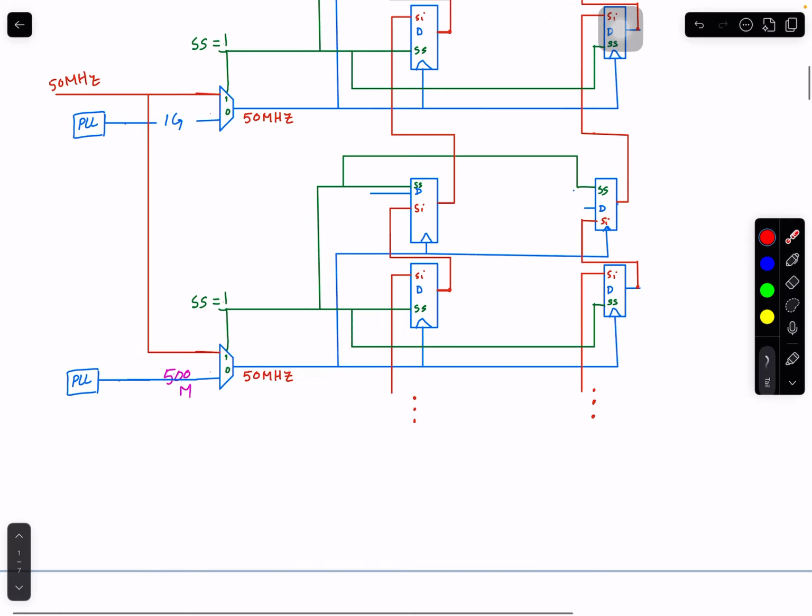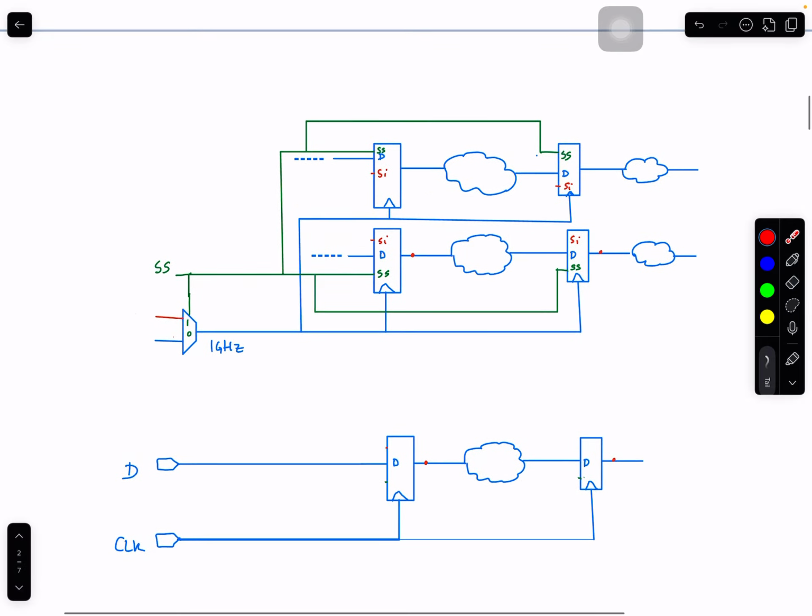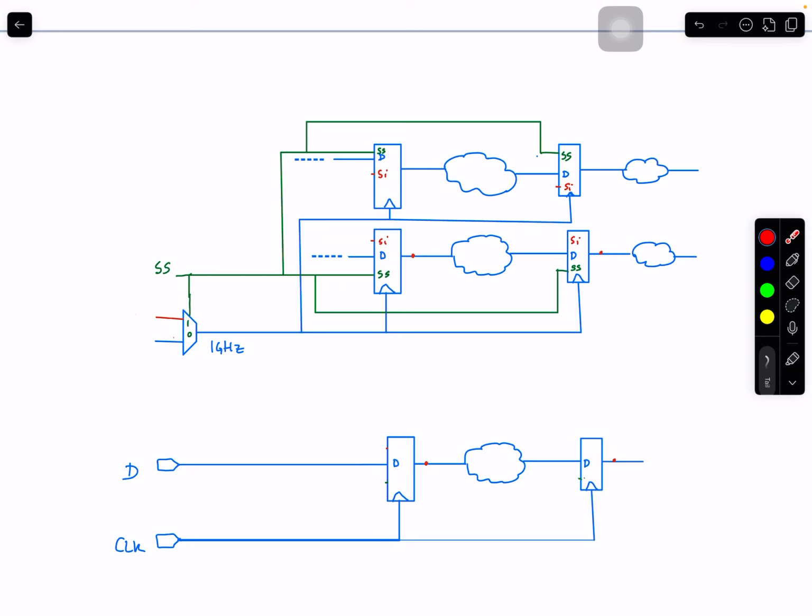You can do that. For example, this scenario that we had in our design that we have been looking at during the training. So you had a JTAG interface. I'm just modeling it with 2 flip-flops. And yeah, this was your system clock, right? Now, in one design, you have both of these types of logic. Now, this clock is coming. Let's talk about only the functional clock. And this clock is coming. They don't interact with each other. No need to have separate modes because they are already independent of each other anyway.